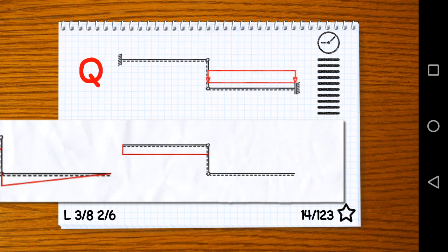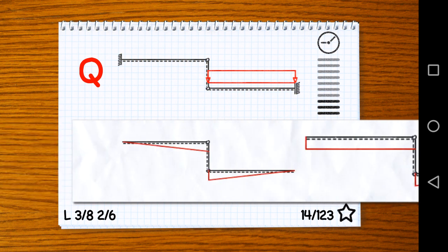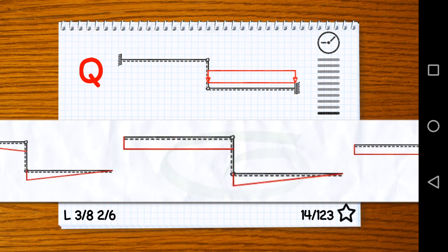Good. Due to the parallel motion, the shear forces need to be 0 at the parallel motion at first, but then have a linear distribution going downward from the right to the left. So this right one here is wrong because that element doesn't have the linear distribution we expect due to the distributed load. This one looks just right. This one here is wrong because on the left element where there's no distributed load, they draw a linear distribution. So here's the right answer in the middle.